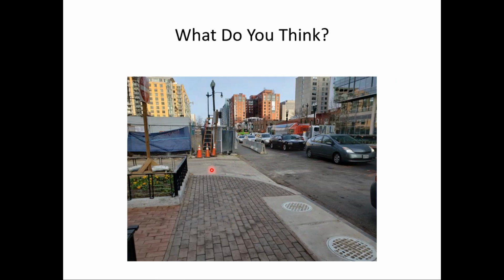It looks like this is a driveway, so you probably can't put devices across here. Also, for pedestrians trying to get in there, looks like there's probably a curb return here. This is probably the level or the flush portion, but pedestrians, say with a mobility device, trying to get there, they may have some cross slope and grade issues with that driveway trying to get into that alternate path.